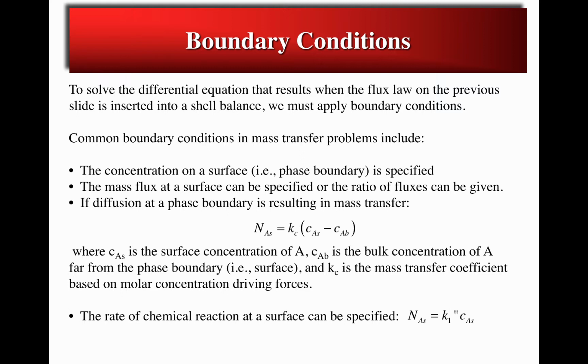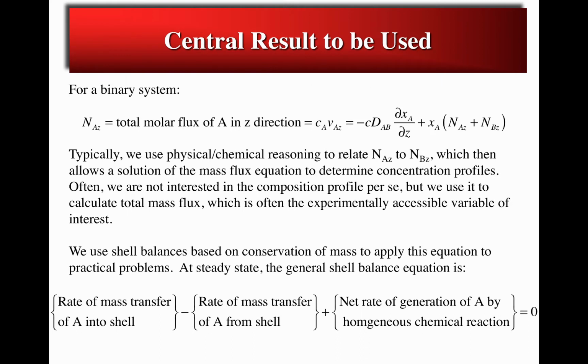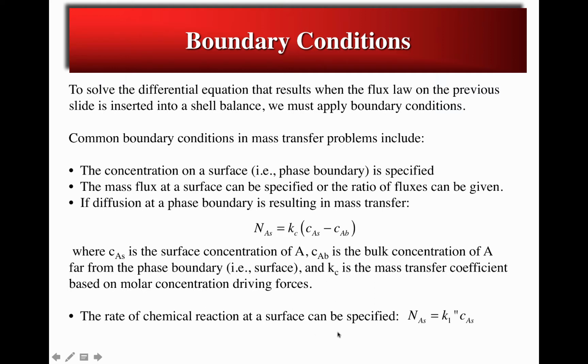And so these three pieces of our problem-solving apparatus are applied to each and every problem that we're going to look at. We have the general expression for the mass flux that's given by the equation at the top of this slide. We have the shell balance that we put this mass flux expression into, and then we have the appropriate boundary conditions, and together then we can solve this for concentration profiles and then calculate rates of mass transfer and so forth.